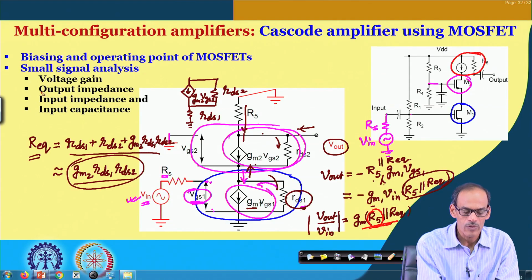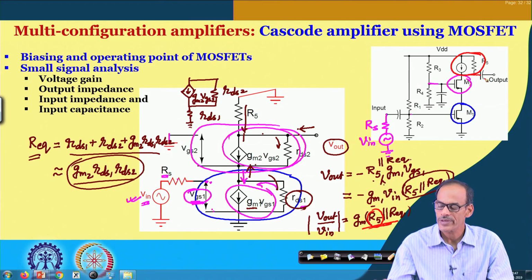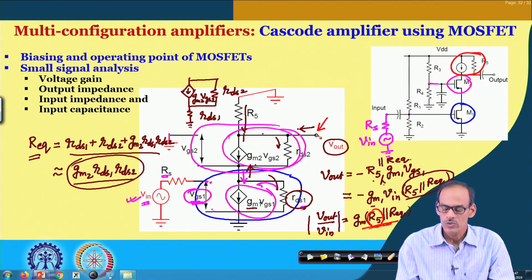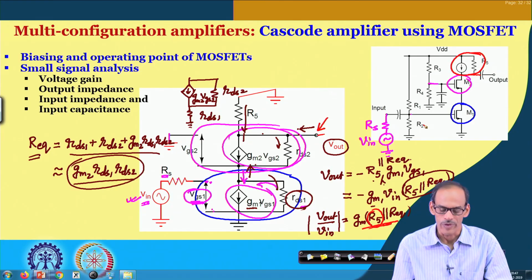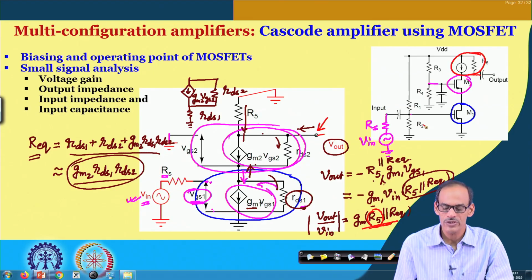But then of course, the output impedance here will be quite high to achieve the gain. So, if we try to directly sense this voltage through some subsequent circuit which may offer a significant amount of capacitance, that may limit the bandwidth. That is of course an issue that may be addressed by putting a buffer here, namely a common drain stage, which we already have discussed.